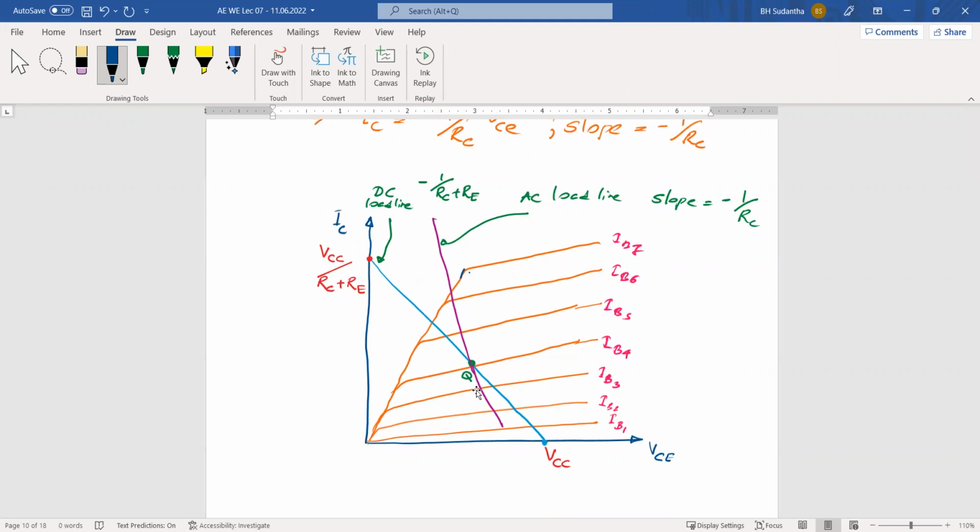We have carefully selected these RC, RE, RB values to put our transistor at the middle point of the graph. After that, our Q point, the operational point, may be in the middle. But when the surrounding temperature increases, the circuit temperature will increase. Then the transistor's inside temperature will increase. Because of that, the free electrons will increase. Then the inside conductivity of the transistor will increase. Then it will badly affect the circuit operations.